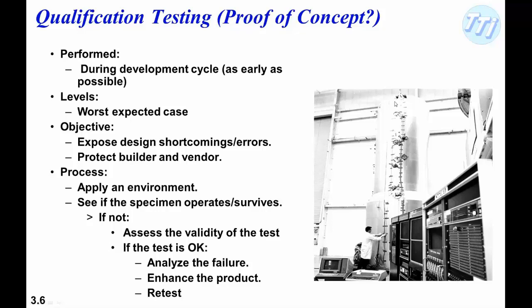And these were simulated with big aluminum plates, and we put accelerometers on those plates and shook the specimen with little tiny shakers that were down here in the area of the control moment gyros. And the objective here was to see whether, when we were exciting the specimen with a few pounds of force, we got acceptable motions or whether we got smaller than acceptable motions here on the two mirrors.